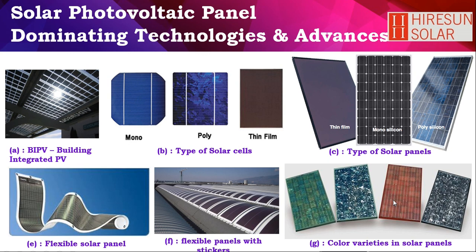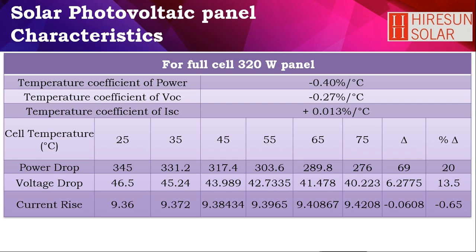But usually Indian weather is good for the polycrystalline material. And in the previous sessions we have also discussed the orientation of the panel. That is, the panel is oriented towards south because we are in the northern hemisphere. So ultimately the polycrystalline panels are generally installed oriented towards south at an angle of latitude. So with this we will start with the design.